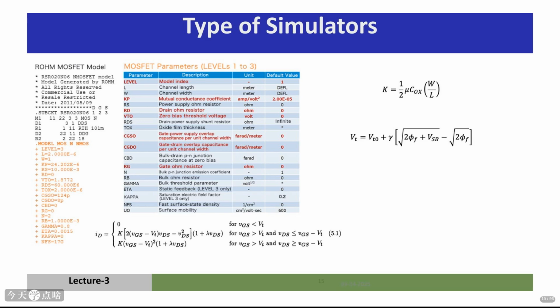These are all physical characteristics and electrical properties. RS, RD, RB, gamma, ETA, kappa, NFS. These are model parameters that fine-tune the behavior. It's a complex set of equations, often derived from physics, that the simulator uses to calculate the transistor's response.